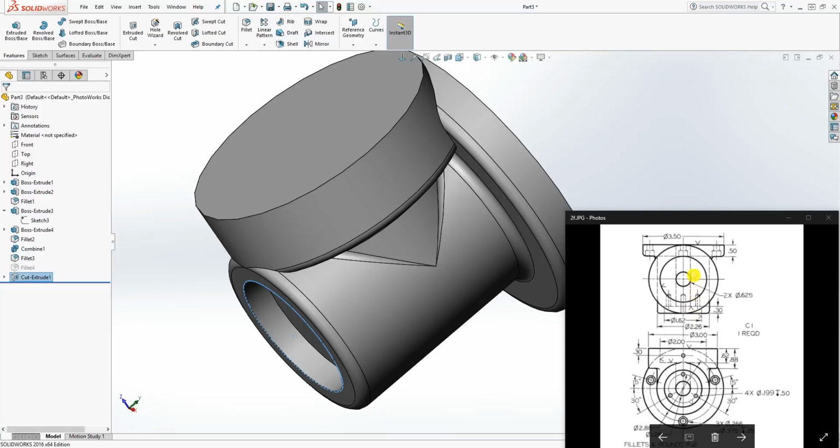And if you look, there's another cut that goes all the way, but they don't tell you what that dimension is. But the way you would determine it is you can see that it is tangent to this circle. And the dimension also tells you that it's 2 circles, 0.625, meaning that that circle is this one and that one going up.